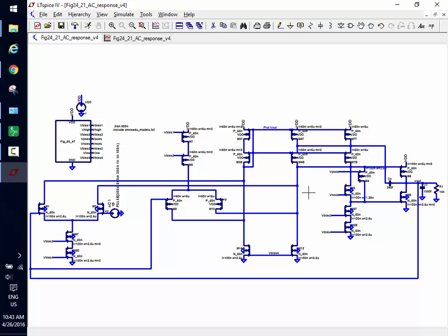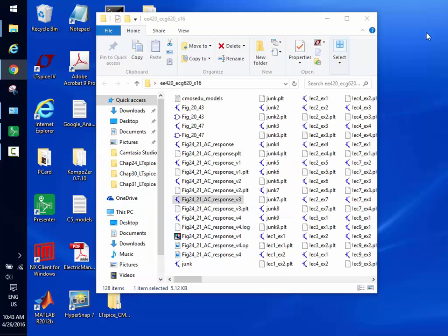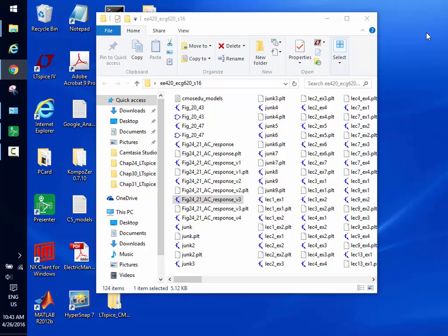I didn't exactly understand the wasteful part. You said we don't need those. Okay, so you see these two transistors are exactly like these two. These two we could replace with a single current if we didn't have it, so that we could put these in the middle here with this. In other words, we move this, this, this, and this over here and get rid of these four. Okay, we'll do that hopefully today, but maybe next time. You're saying it's just redundant. Well, really, they serve no purpose, as far as the way that they're wired. They don't do anything. The ones to the right should be in the middle. Yep, exactly.